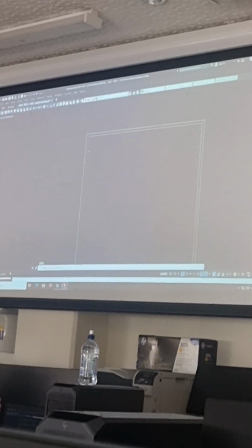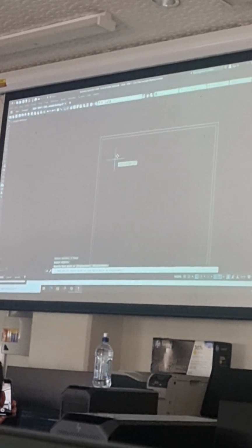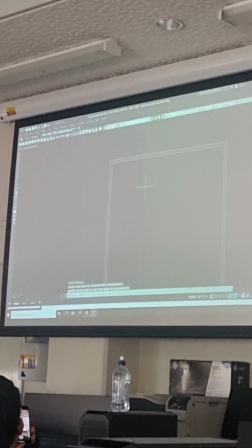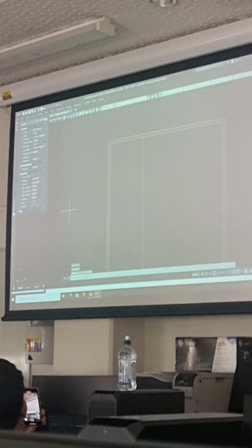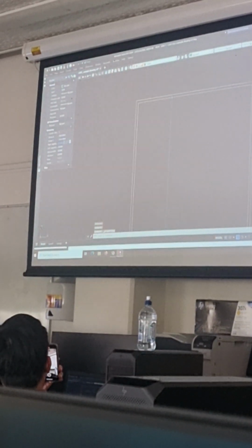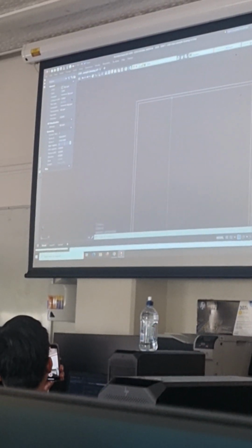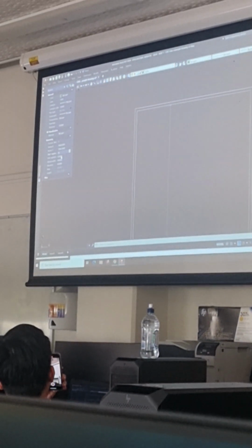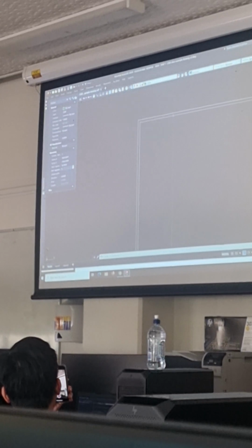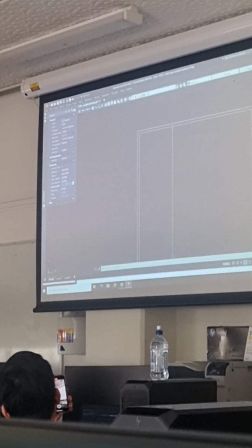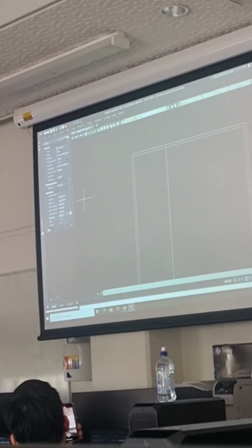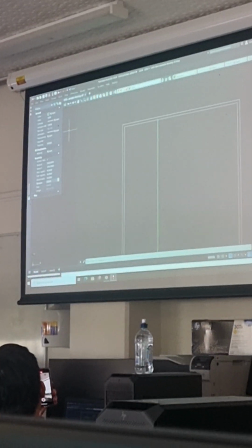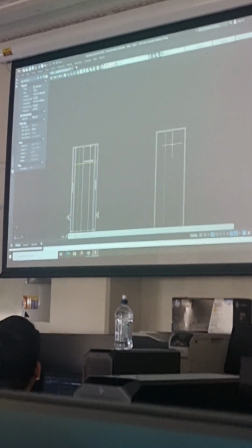Now I can move this anywhere I like along here, and I'll go right click properties and start segment 16. I'll check that in a minute. End segment 16, global width 16. I could have actually just gone for global width, but never mind. I wanted to be different.